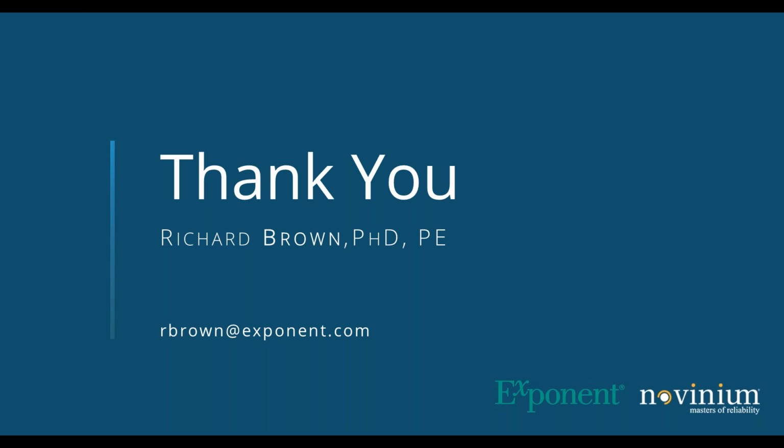And I'll say that right now, non-age-related failures for all of these analyses were backed out. So if there was, say, a dig-in, that was not included in any of these failure rate models. If you did have some sort of a fault, that would generally be what a failure would constitute. This utility didn't do any partial discharge testing or anything like that that resulted in any replacement. So they were just faults that occurred on the cable system.